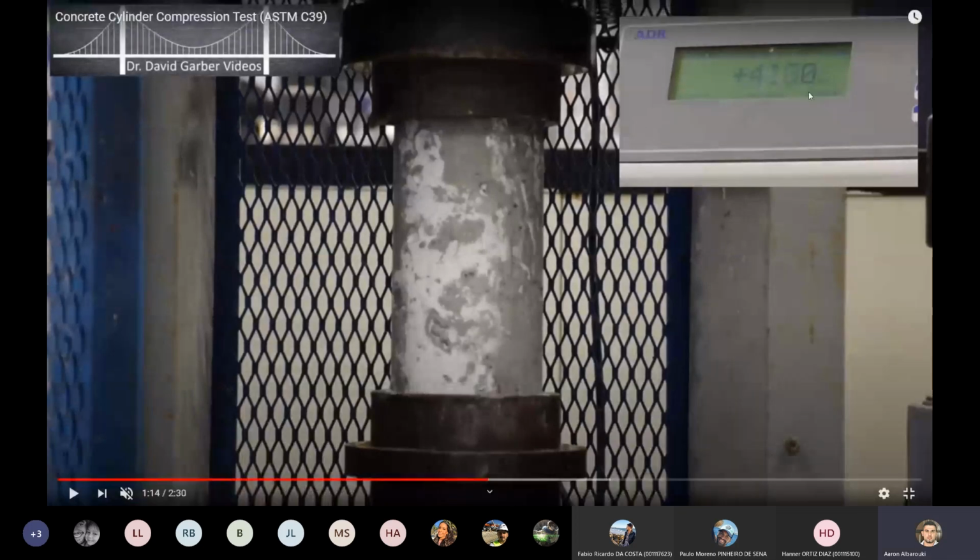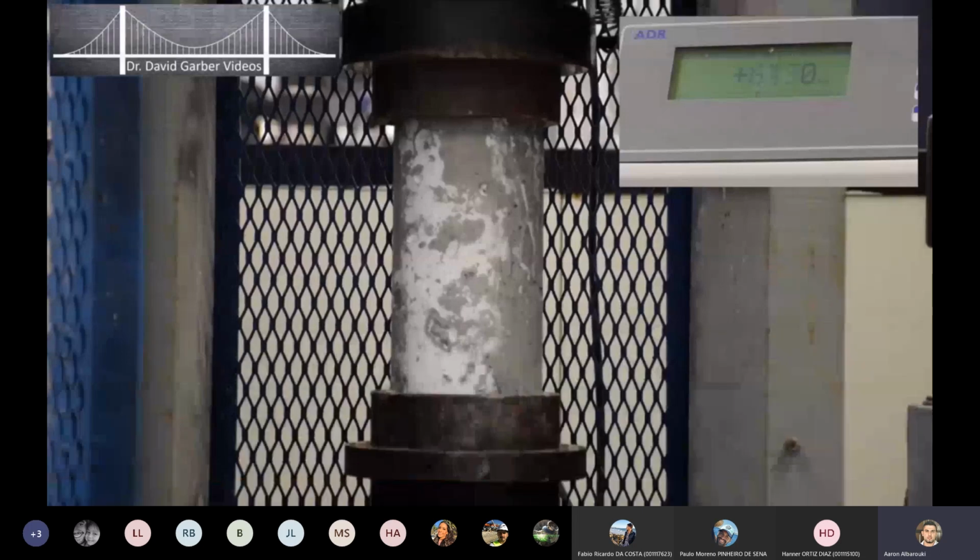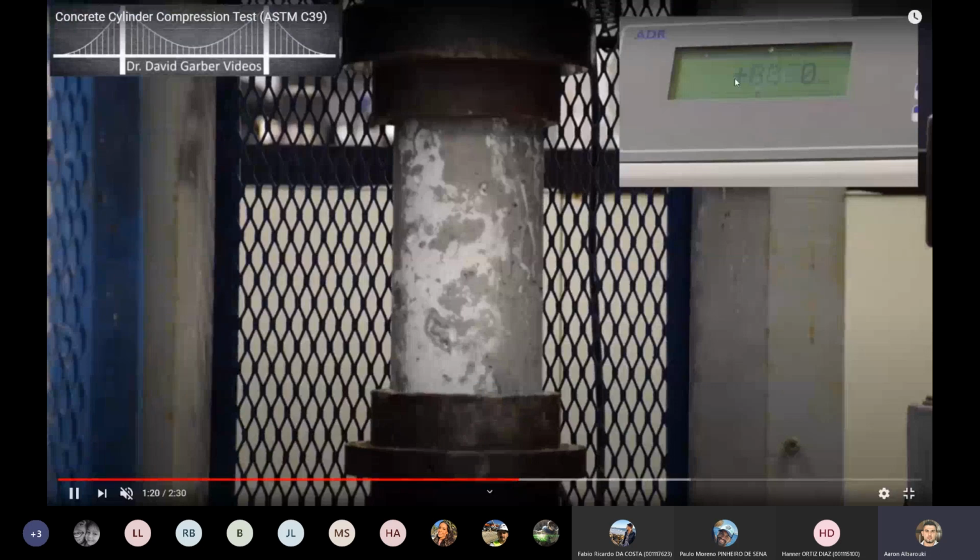So these numbers here are in American units, pounds, so don't stress too much about them, but it's the general principle. If we measure the maximum force here, what we get from there divided by the cross-section area, by the time this will fail, you'll see in a minute.